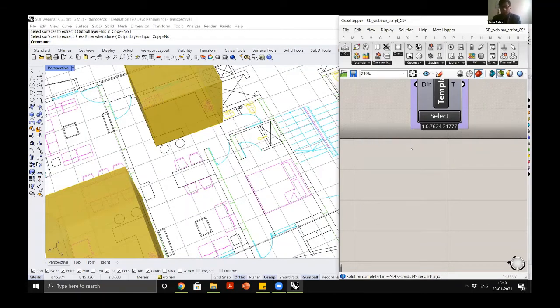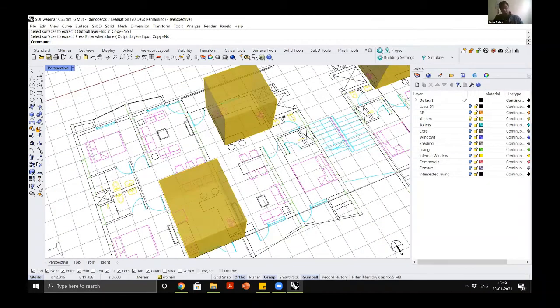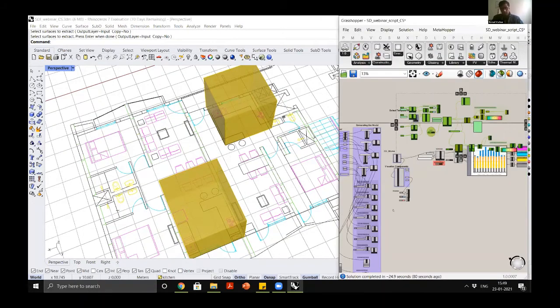Or if you are following, then you can do that. But when you have your air temperatures, operative temperatures, and relative humidity from each and every zone, then that requires post processing. You will have to take those hourly values into maybe Excel and then compare it with your IMAC band, compare it with your thermal comfort threshold. Then you will be able to get your comfort hours.